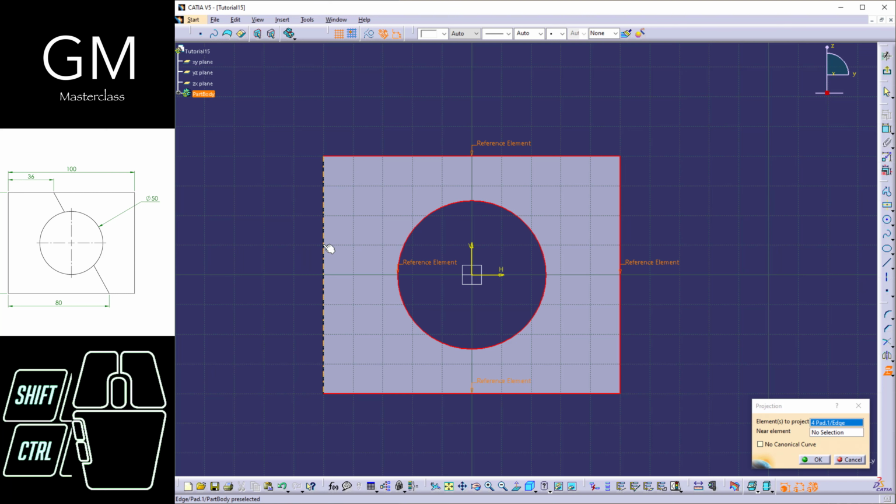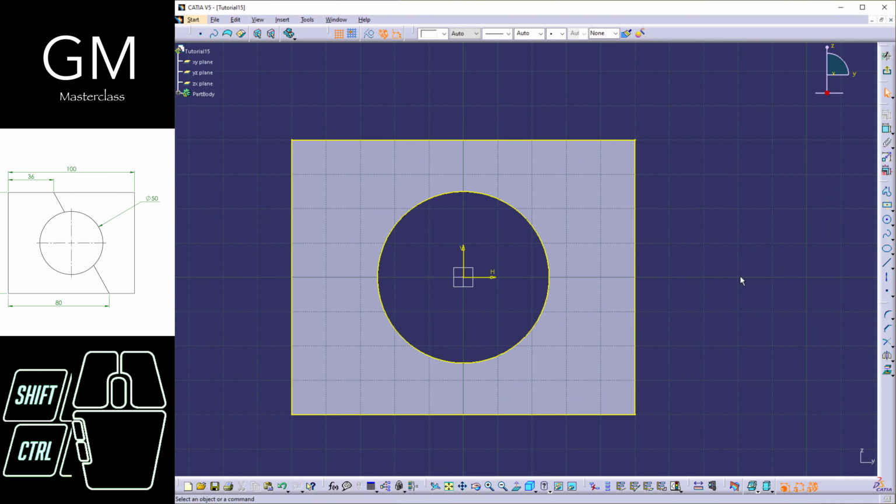So for example, I want to call all the lines that I just did, so okay, and then Control C to select all the lines that I've selected previously, but I want these lines to be meant for construction purposes, so I'm gonna click right here, and then I'm going to create one profile, but deselecting this tool, right, because I want these lines to be shown.